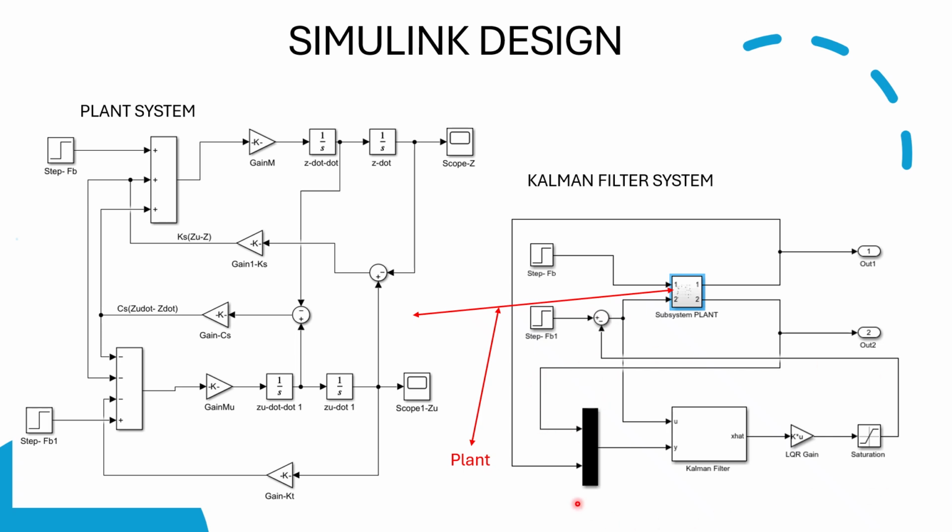by basically adding a Kalman filter and an LQR, again with a saturation of about plus or minus 1500 newtons. That is what really creates the active system, because the Kalman filter sort of mimics the actuator design in this project.